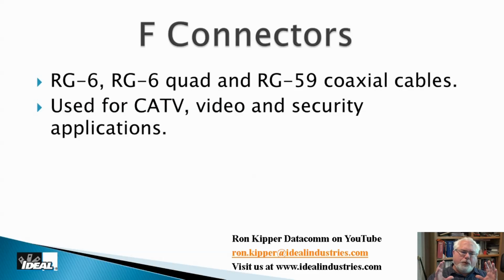A dirty little secret about F connectors and about coax is that they don't always fit together, even though they're both RG6 or 59 or whatever it is. What they don't tell you is that when they manufacture coax, RG6, 59, from manufacturer to manufacturer, they're not always the same dimensions. It's more of a guideline than an exact dimension it has to be. It's more of an electrical spec than a size kind of thing.